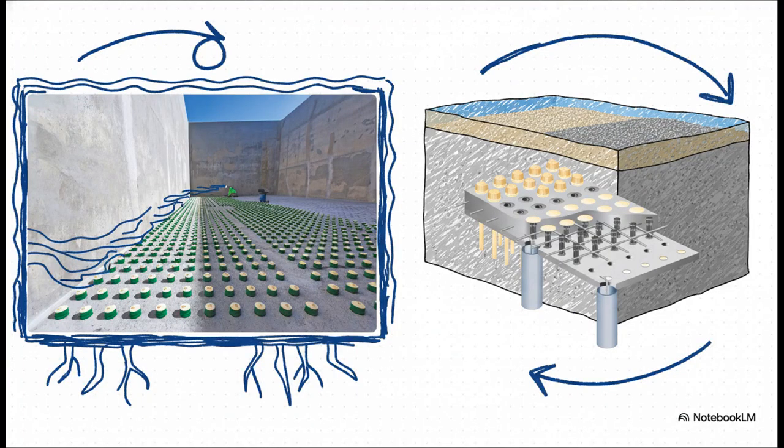Moving right along, Section 2, under drains, the hidden foundation. Now, the physical, completely unsung heroes of this whole process live literally on the concrete floor of the filter tank. On the left, we've got a real-world look at these specialized nozzles laid out across this massive concrete floor. And brilliantly illustrating this on the right is a 3D cutaway of what we call a monolithic filter underdrain.